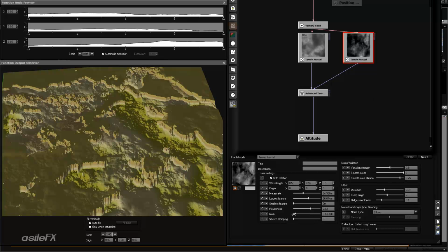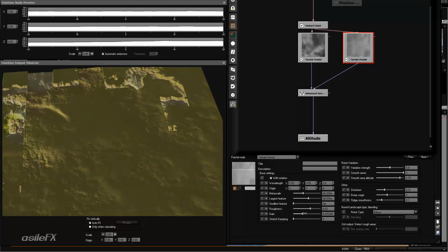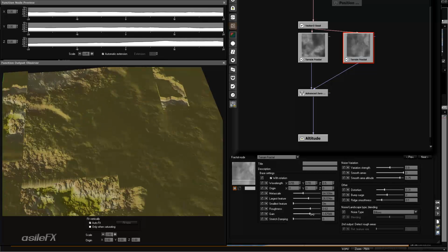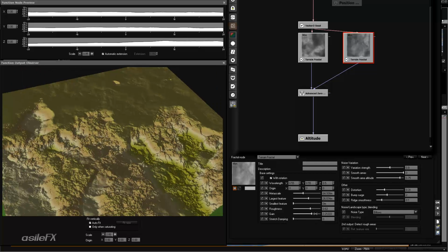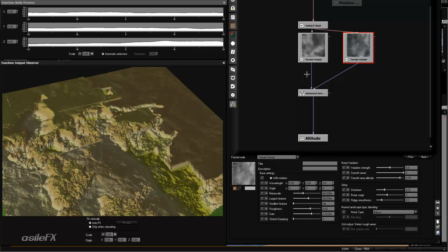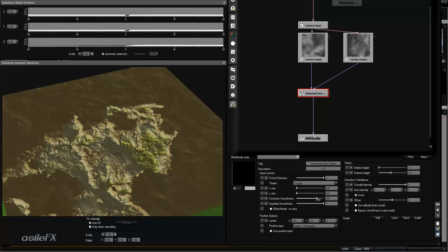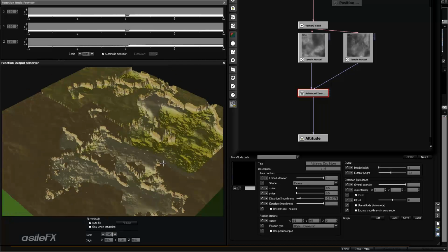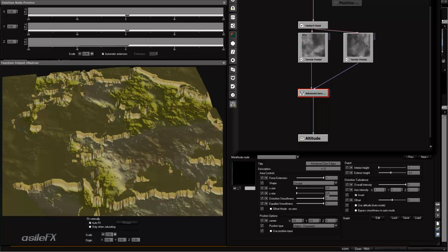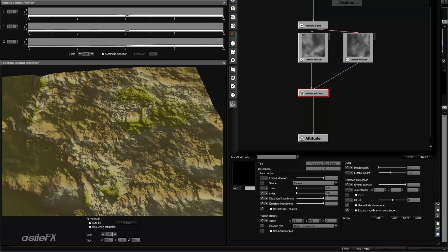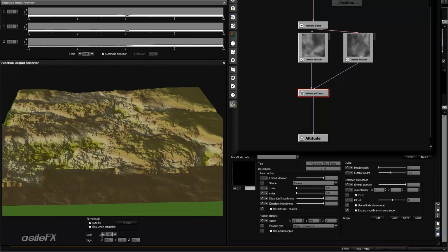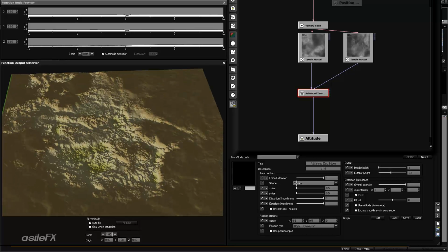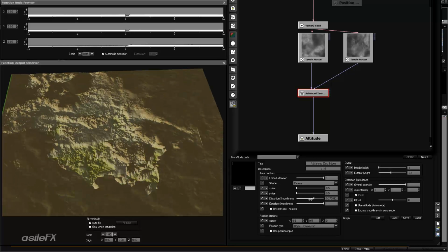Depending on the distortion, we can change the gain to smooth that out, or we can use the smoothness values. With our distortion smoothness, lowering it is going to create a sharper cutoff. Increasing it up to 1 is going to give us the full blend and a full amount of smoothness based on the fractal, or whatever the distortion input is.